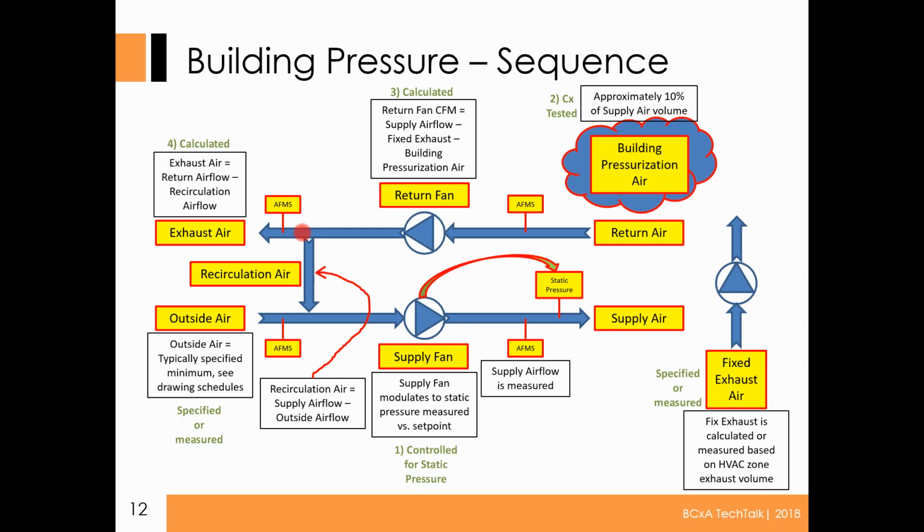So yeah, I can't give you the magic formula, but you definitely need to start looking at the data. When does this happen? Is it when I'm only at 100% mode? Is it when I'm at minimum mode? How has this offset between the two been determined? And overlay the pressurization trending to see what my pressurization looks like. Again, I would go into full troubleshooting mode: what's the range of the sensor? How is the outside port being measured? If it's a stormy, windy day versus a not windy day, you want to get some references here and go into troubleshooting mode, because that's not healthy.